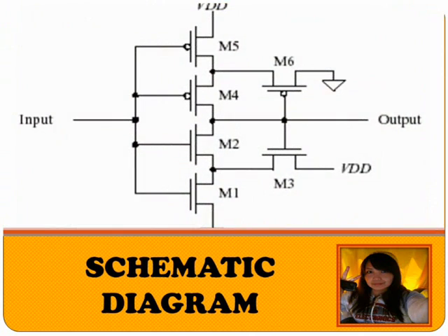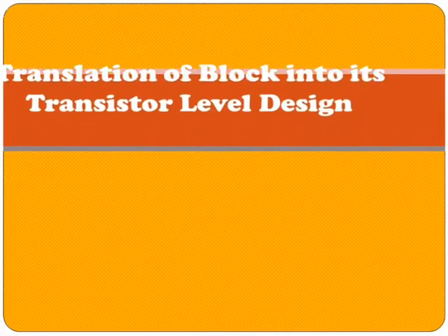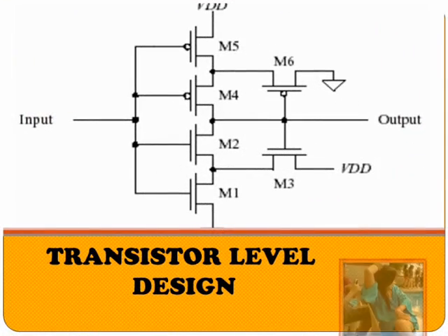The resistors form a voltage divider network biasing the source of N2 at roughly half the supply. When the input is at threshold voltage, 1/2 VCC, N2 begins to turn on and regenerative switching is about to take over. Any more voltage on the input causes out to drop. When out drops, the source of N3 follows its gate, which is out. The influence of N3 in voltage divider with N1 rapidly diminishes, bringing out down further yet.